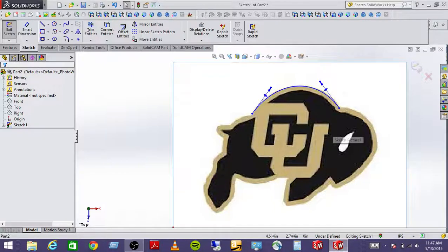Just use lines, right? And then you might use splines on the horn. As long as you make them distinct, when you go over to Corel Draw, you will be able to just grab that one piece. What you'll do is you'll adjust your speed and power settings on the laser. Or you can keep the same settings and rerun the path multiple times.